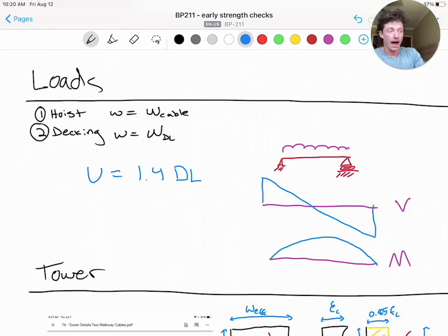And after this, because we're filling in the abutments, supporting the anchors, finishing the ramp walls, things like that, the free body diagram is going to change, and there's going to be more structural support for the anchor. So when we move on with that, as well as after more time, the structural concrete will most likely have reached close to or its full strength.